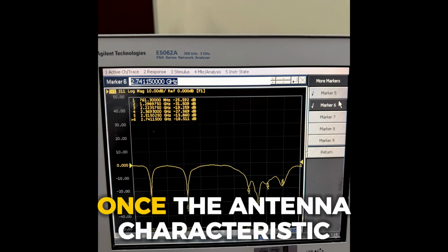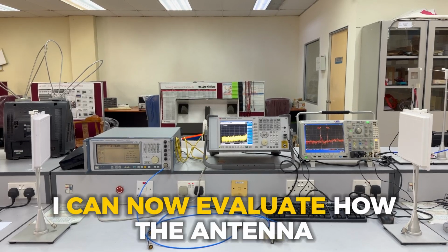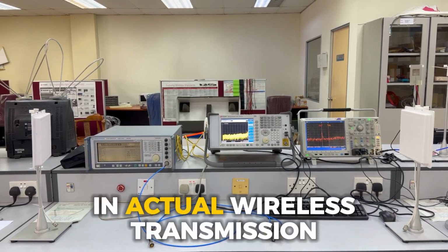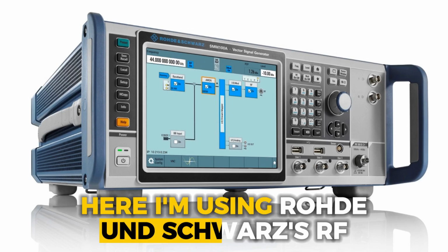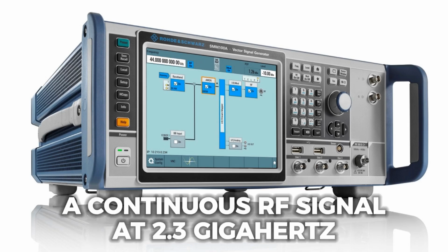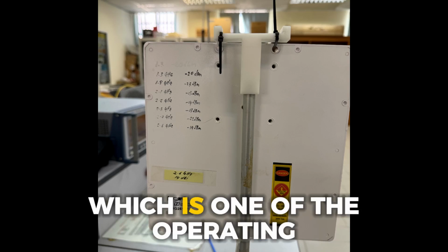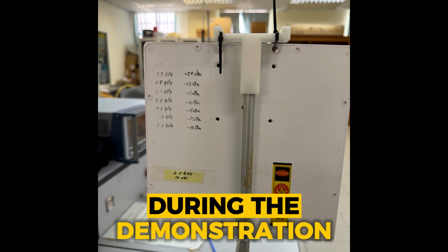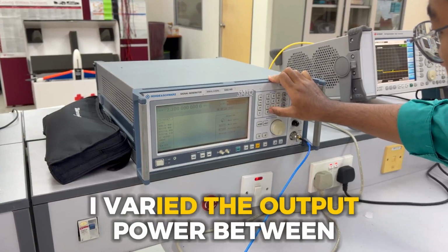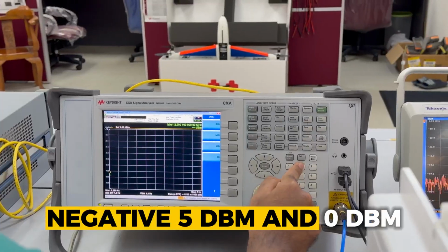applications. Once the antenna characteristics have been verified using the VNA, I can now evaluate how the antenna performs in an actual wireless transmission setup. Here, I'm using a Rohde & Schwarz RF signal generator. The generator produces a continuous RF signal at 2.3 GHz, which is one of the operating frequencies obtained from the VNA measurement. During the demonstration, I varied the output power between -20 dBm, -5 dBm, and 0 dBm.